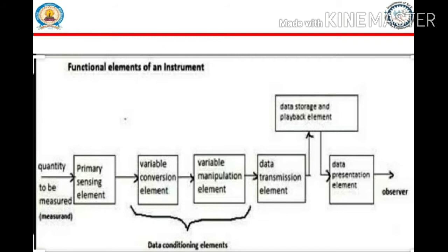For example, suppose you take an electronic weighing machine. In input stage, the weighing machine comes in contact with the physical quantity, the weight which you are putting on the weighing machine. In input stage, apart from coming in contact, the input stage is converting the mass of the object into an equivalent electrical signal. So this is what you can identify in input stage in the considered analogy.